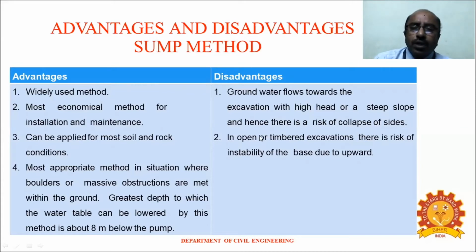And if you go for open or timbered excavations, the risk is there for instability of the timbered excavation, because when you pump out, the water is pumped for a longer distance, thereby the sides may collapse. That is the main disadvantage of this method.